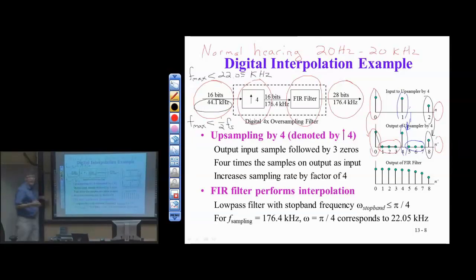And that's all we have. Any frequencies that we introduce at or above 22.05 kilohertz would be artifacts. Could be harmonics, could be replicas of, because we know that this is really just a sampling operation, this upsampling. And what we actually are going to get in the frequency domain is replicas of this baseband, of this low-pass signal, replicated at high frequencies, like we would in sampling.